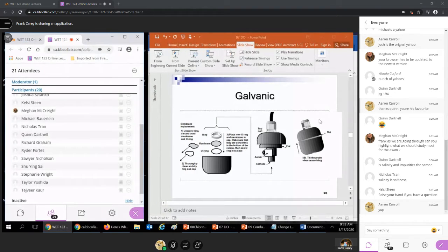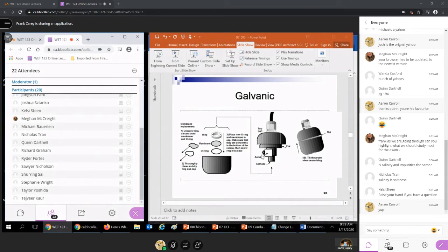So this is a breakdown of the galvanic probe. Basically, you would unscrew this, and inside this probe is a caustic solution that will interact with the anode and cathode. So I'm going by memory. I do believe that the anode is gold, or cathode is gold, the anode is lead for galvanic, but potentiometric or polarographic, it's platinum and silver, I think.